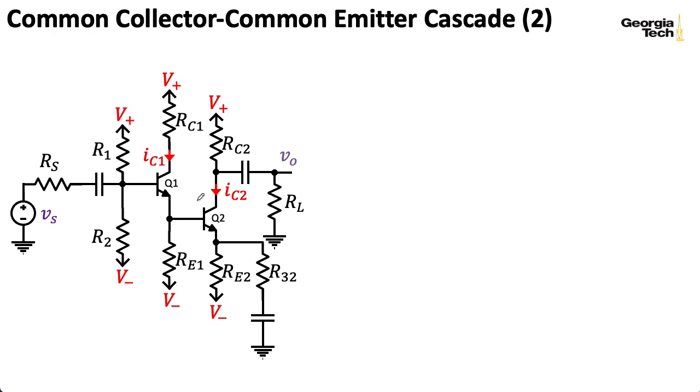So most textbooks would probably analyze this kind of cascaded amplifier structure by treating these two halves separately, computing the output impedance of the first half and computing the input impedance of the next half, and using a voltage division rule for the interface between them. Here, I'm going to use Marshall Leach's technique of just doing everything in terms of Thevenin equivalent circuits, where I can just kind of write down the answer.